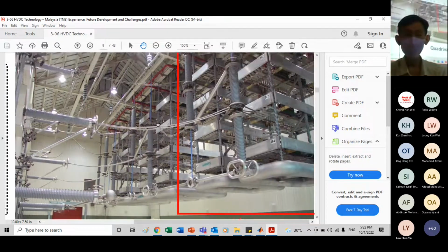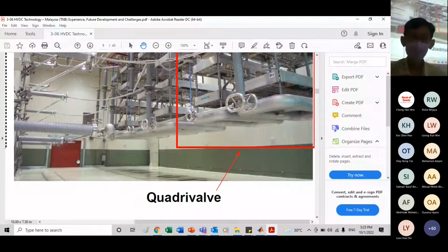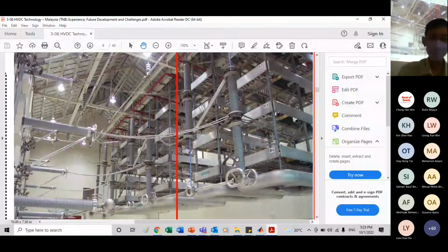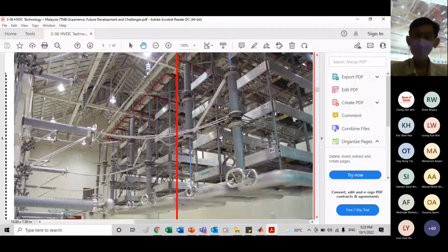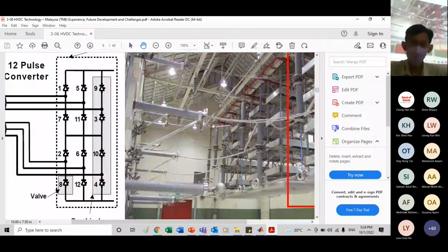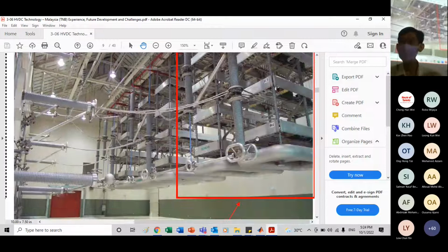And this is the door. You can imagine how huge that is. And it is water cooled. That means it will be very, very hot. So these are the rectifier sets. 2, 4, 6. So 6 sets. Then you may see how come it's so big. When you open up, it's just a series of diodes connected in series like what I explained just now. Series increases the voltage. Parallel increases the current. We are no longer dealing with 1 amp, 2 amp here. We are talking about kilo amps.